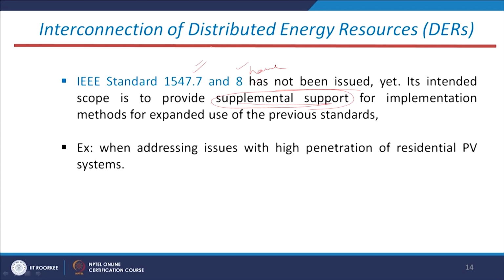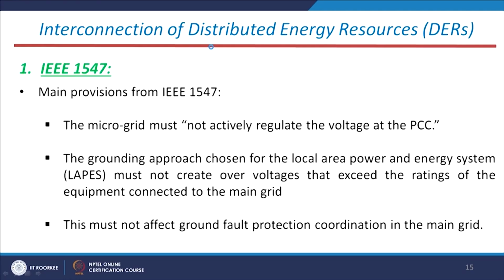So, these are a few of the standards of the IEEE 1547 series. Now, I will tell you some very important points as far as 1547 is concerned. The first one is that the microgrid must not actively regulate the voltage at the PCC. What is the meaning of this? I will draw a very simple diagram.